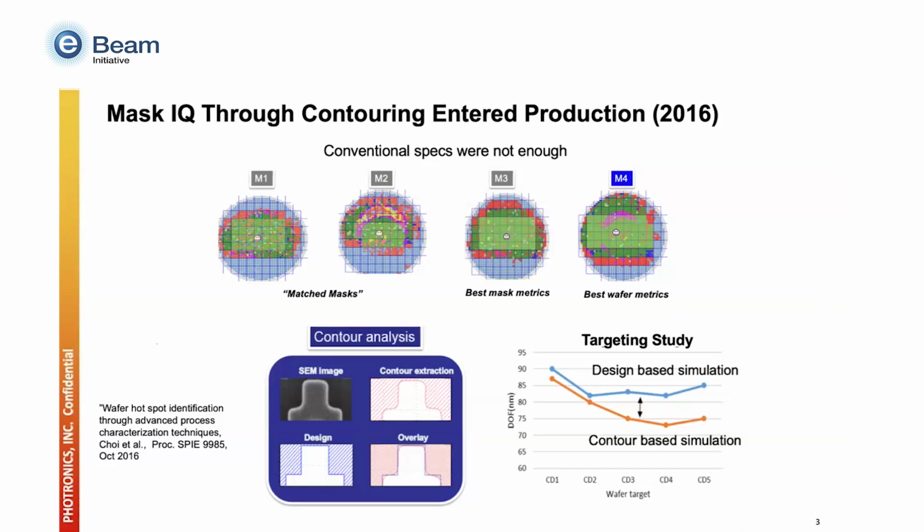If you draw your attention to the left, M1, you see some number of good die. Then going all the way to the right, M4, you see a larger number of good die. What we were trying to do with this customer is understand why the first two masks, mask 1 and mask 2, presented very different yield characteristics that really weren't particularly good. And mask 4, which actually had a poorer conventional mask specification, produced much higher yield. We measured it lots of different ways, and we were able to correlate the yield directly to these mask parameters. So that was the interesting question we tried to answer.